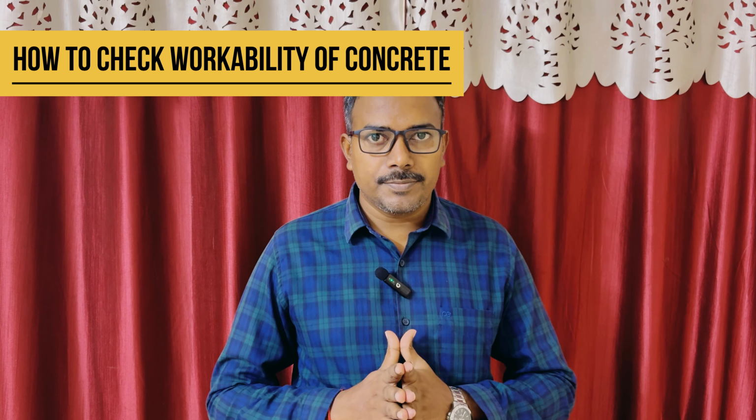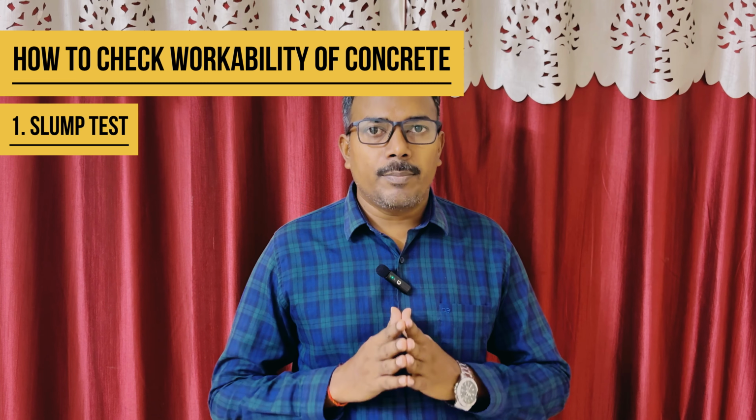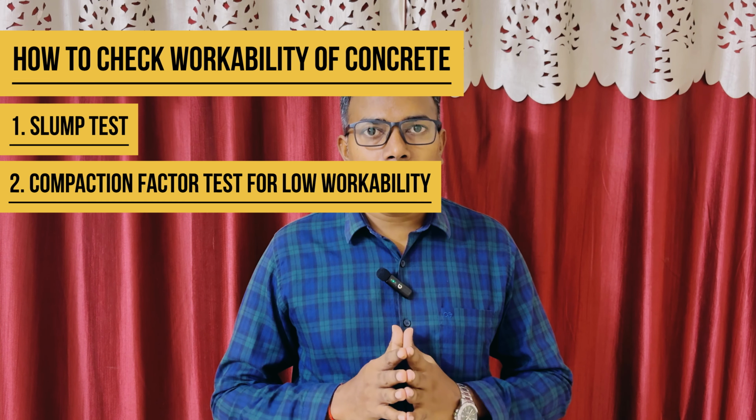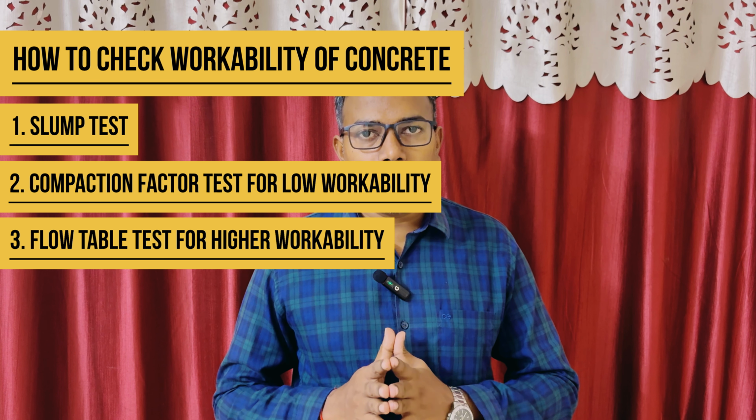So the next point is how to check the workability of concrete. The first is the slump test, which is very common at site. The second is the compaction factor test, which is especially for low workability. And the third is the flow table test, which is for higher workability. So boom, we have learned workability of concrete.